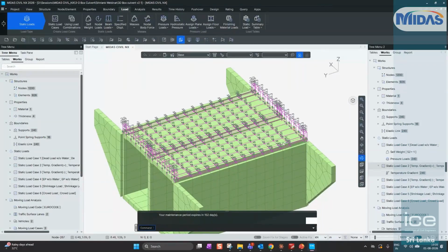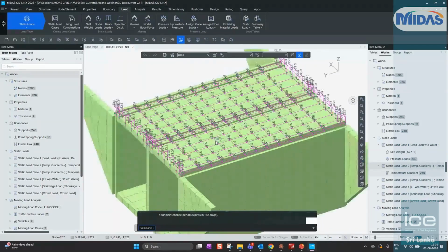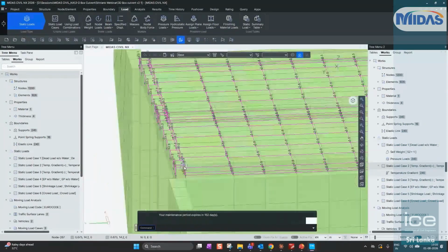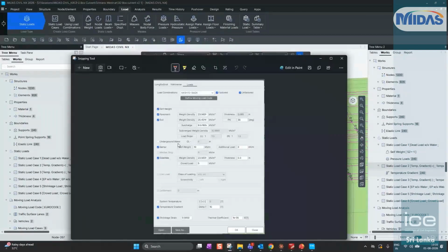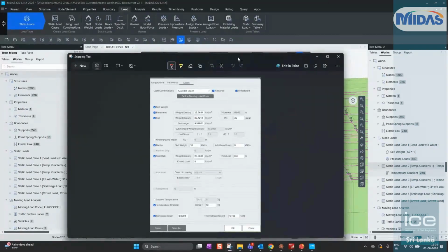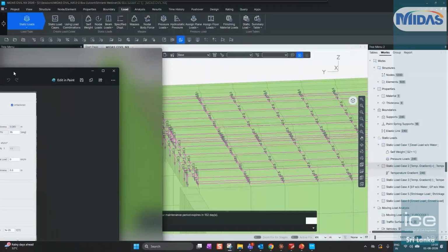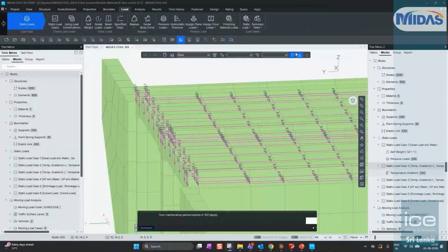Now here you can see that in these zones we said that we have a higher loading as well. So we said that there's a dead load of this one. So you have a crash barrier load of 10 kilonewtons per meter, and then the crash barrier thickness itself was around, I think, 0.3. We can check that via meshing.